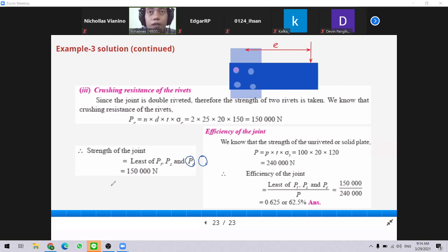And about weld, it is also a permanent joint, and it has a continuous joint area, so it will have larger joint load distribution. So it will have higher efficiency. Theoretically, it will have higher efficiency compared with the rivet joint. But as we know, not all materials can be joined by welding.